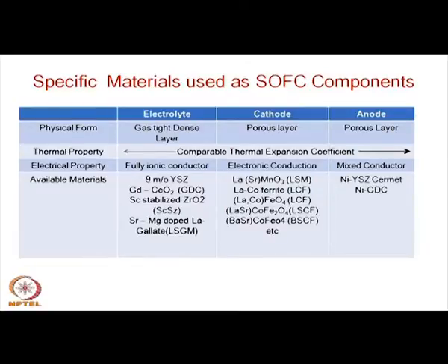If the thickness is large, then the resistance is high and the current density of the system as a whole reduces. Therefore, any design will tend to have a very low thickness, in the order of microns. It is not even millimeters, the electrolytes are in the order of a few tens of microns. That is another requirement of the electrolyte, and it has to be completely dense.